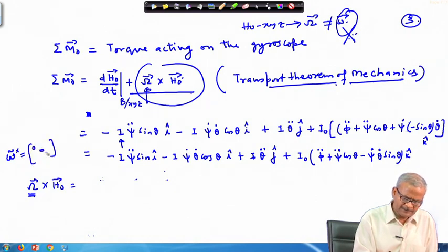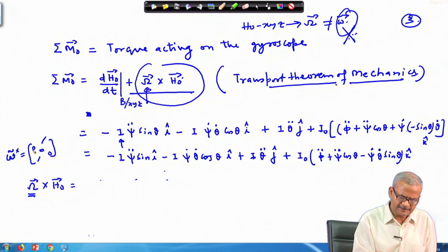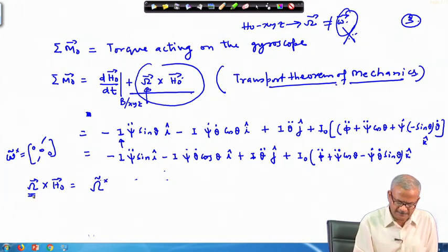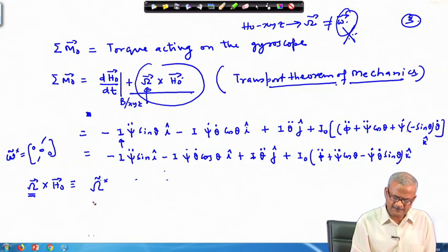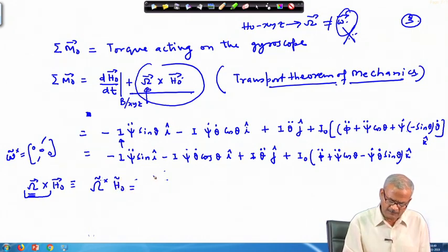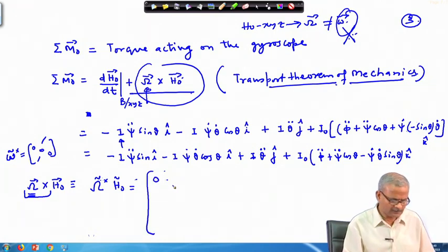a skew symmetric matrix. Okay. On this side there will be something, this side, and the diagonal elements will be 0. So, here basically this quantity is your, you can write it like this, omega tilde cross. So, here it is written in the form of a vector, here you can write the same thing in the form of a matrix, means this part basically you are replacing by the skew symmetric matrix, and this is S 0 tilde. So, in the skew symmetric matrix, this component is 0, and then put the other components here.